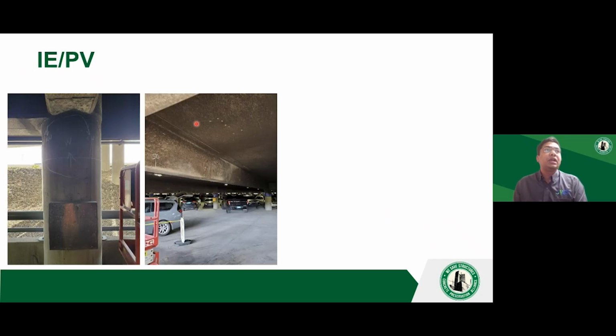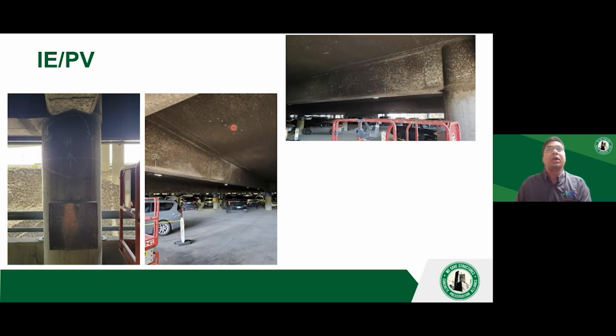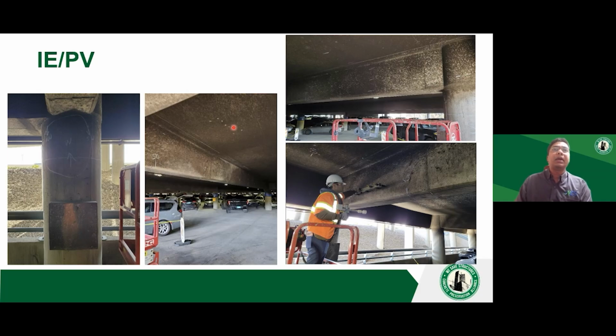This is a really good case study where they had a car fire in a garage in New Mexico, where the beams, the columns, and the slab under the deck were affected by really high temperatures because of the fire, and that resulted in compromised strengths of the concrete. And we were tasked to determine what the compressive strength of the concrete is. So we did impact echo testing of the beams, columns, and the deck underside.